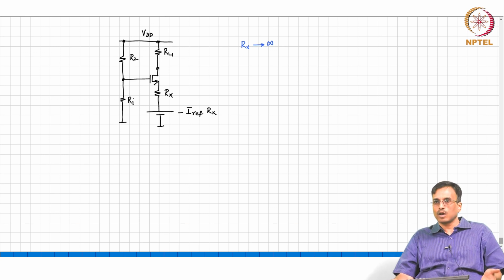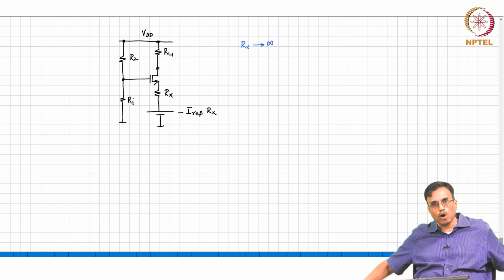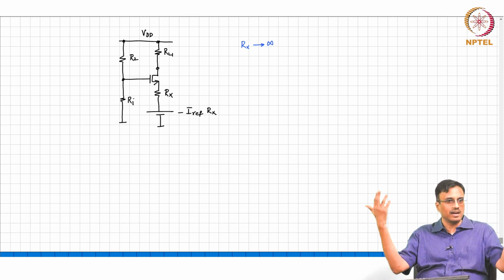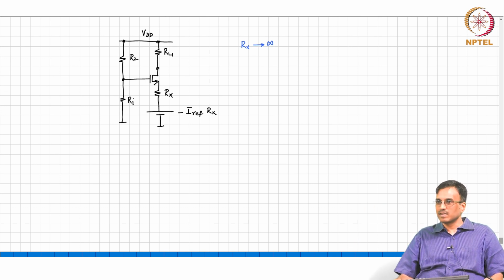And what effect will that have on the branch currents in the network? If I take all the nodes in a network and move all their potentials up by the same amount, what will happen? It's like giving everybody in the country 2 crores, and in India, everybody is a crorepati. You understand? That's not helping anybody. Correct? Because flow of money only depends on differences. Correct? Like flow of current. So, if all the voltages have gone up or gone down by the same amount, basically the currents in the branches will not change.